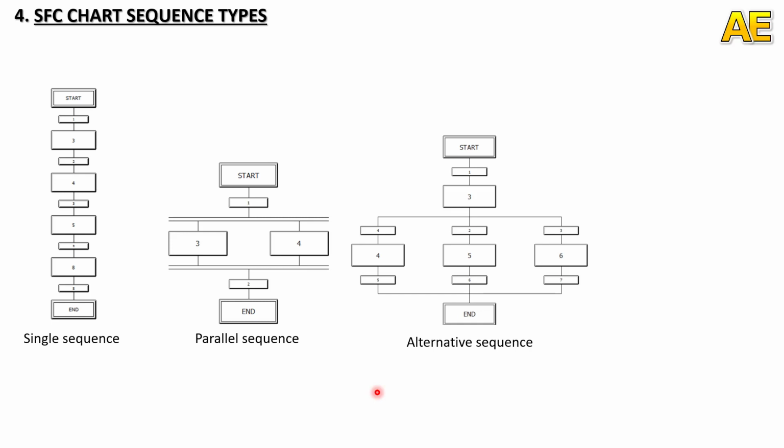In an alternative sequence, every transition should have parameters defined at the start of the step. Transitions without parameters are always true and therefore automatically satisfied. This means they are always true before a transition with parameters.